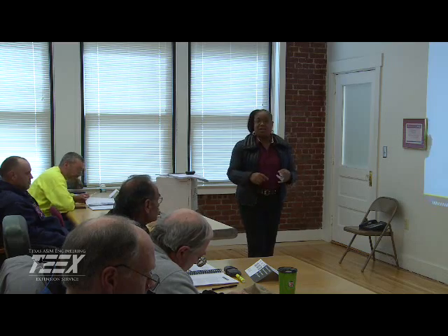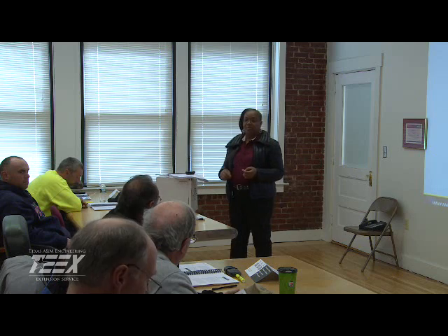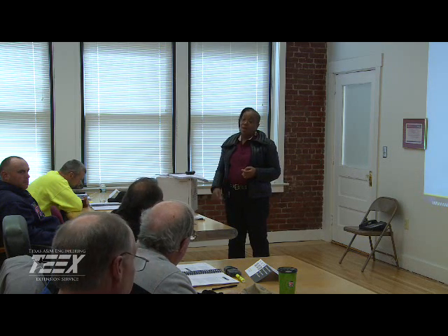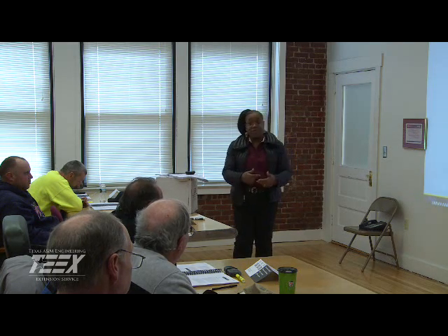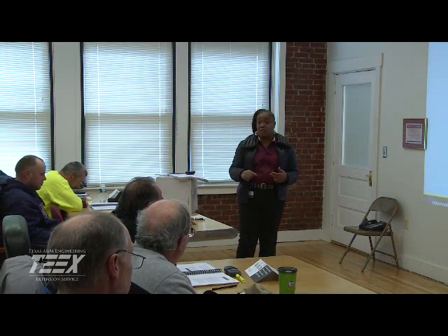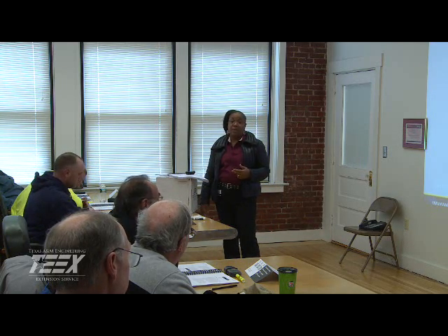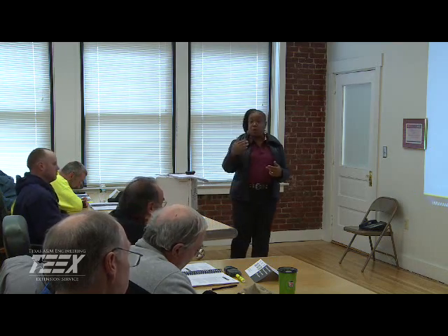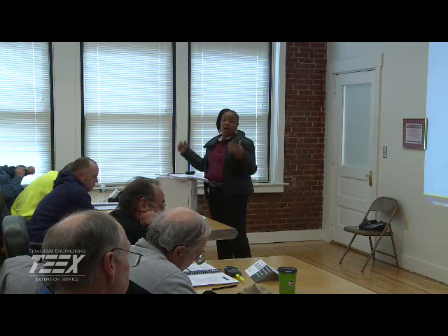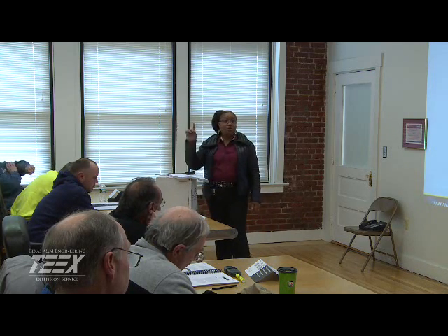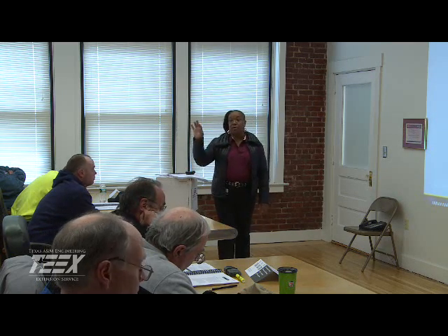Suppose they all pop. If they all pop, now again, I'm into that situation where I have to retest, and I'm taking 5 more samples the following month, and I'm following up with the public notification also. Absolutely. And I may be thrown into corrective action at that point, especially if they all come back positive, as opposed to 1 or 2 of them. If I have more than 1,000 people, that's where I'm collecting 3 for every positive that I get. Okay, understand? Make sense? Good.